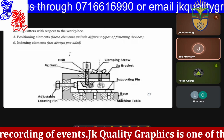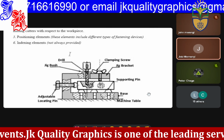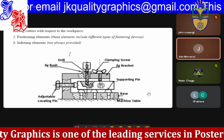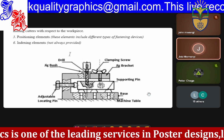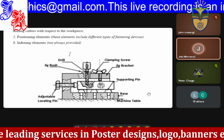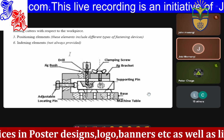Or sometimes you can do drilling. You can make holes around a circular plate, and for you to achieve accurate positioning of such holes around a workpiece, you need an indexing element which normally turns together with the workpiece. While you turn the indexing element, the workpiece also rotates or changes position.